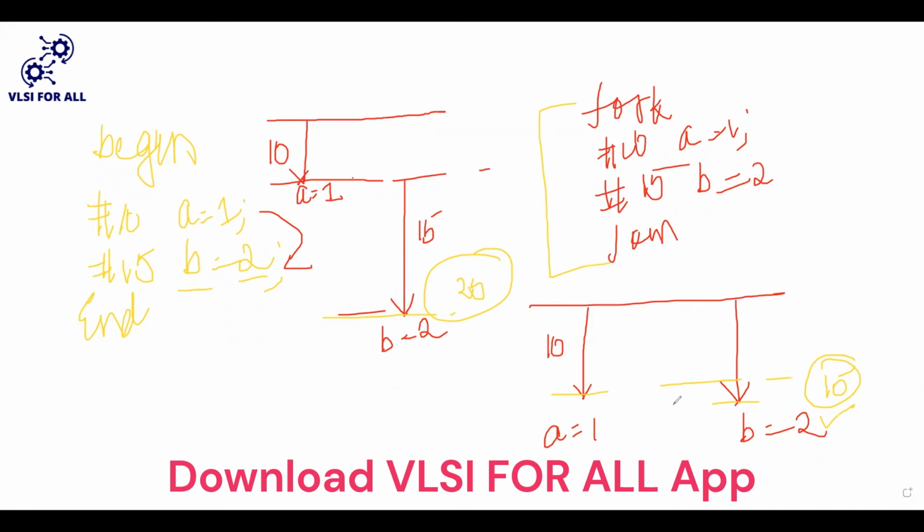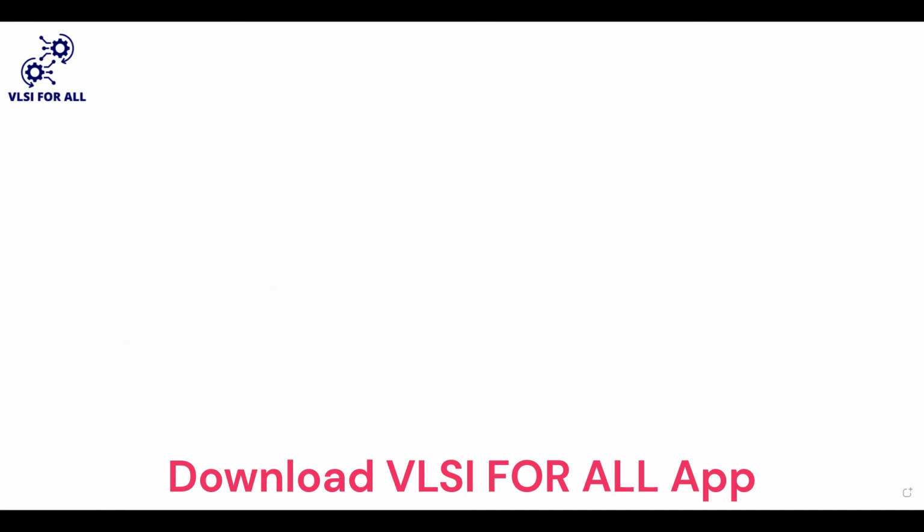There is one more thing, like Verilog is a concurrent language. Inside the concurrent language, for a few statements to execute procedurally, we again use procedural blocks. And inside the procedural blocks, if we want everything to execute concurrently, then we can use the fork and the join blocks. So this is the fork and the join.